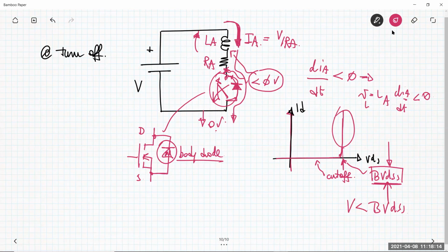But anyway, the mechanism by which this MOSFET destroys itself when you operate it at the breakdown voltage is related to a thermal process that is involved inside the semiconductor material of the MOSFET. And this involves also the thermal capacity of your devices.